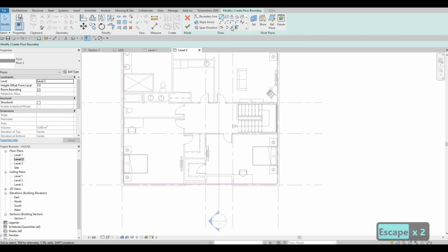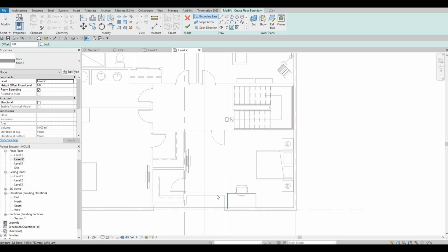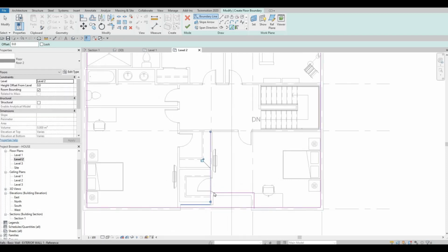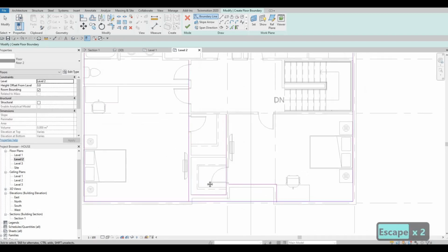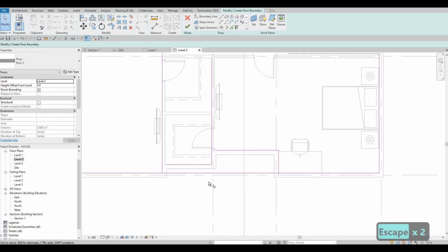After that, I'm going to use pick line and add the ones that are from the and then let's use trim, and then here we need to type in SL, so trim and so that's split, and then TR. Let's trim this.